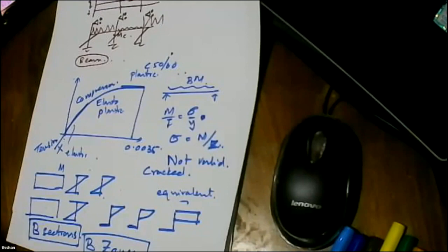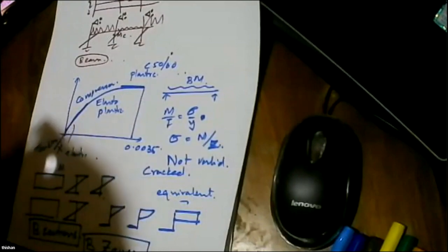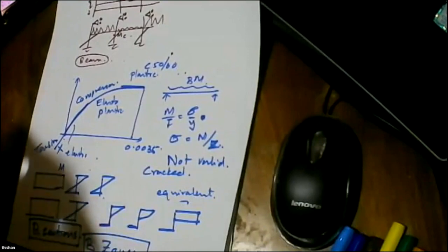The moment you develop bond, the bond can be as high as 400 or 600 kilonewtons per meter square under service conditions. So if you are going to get that type of very high values as the skin friction, and if we socket long, even though the rock is fractured vertically, the confinement is very high, and we will not have any problem.